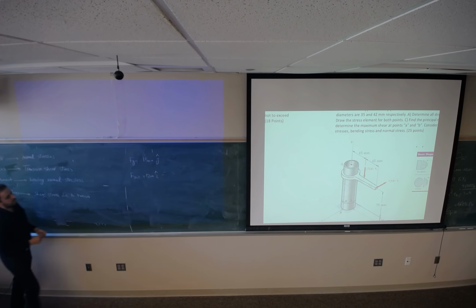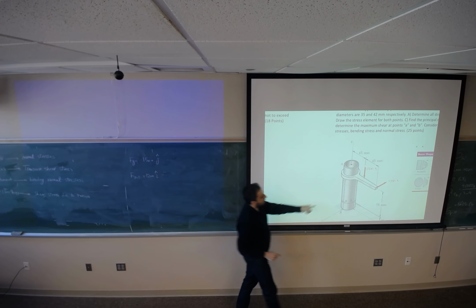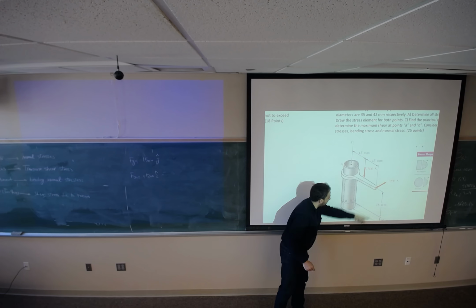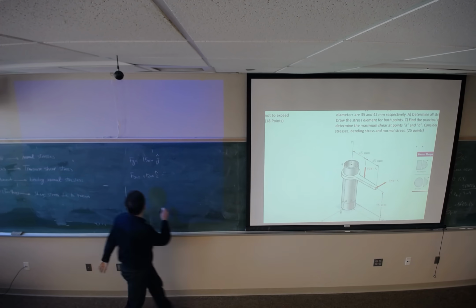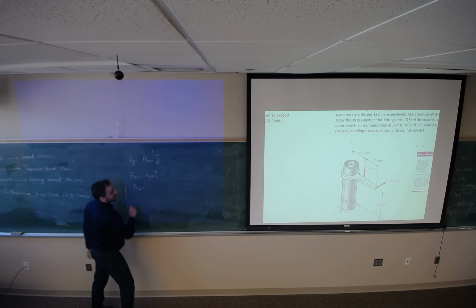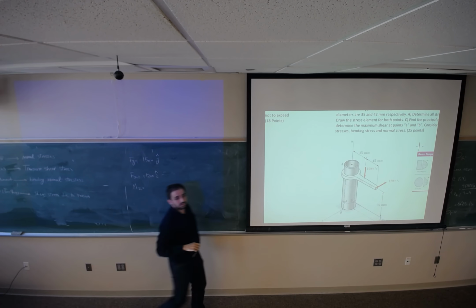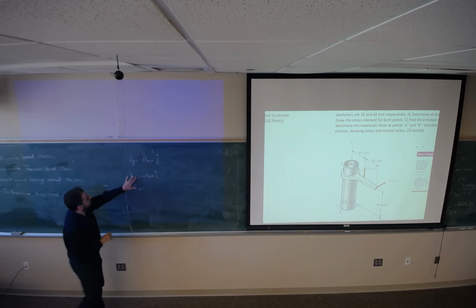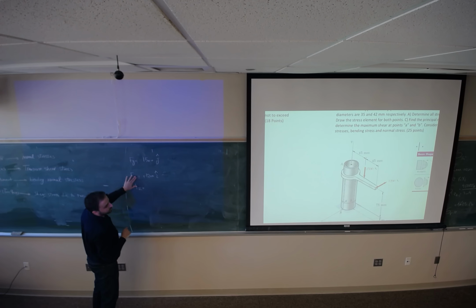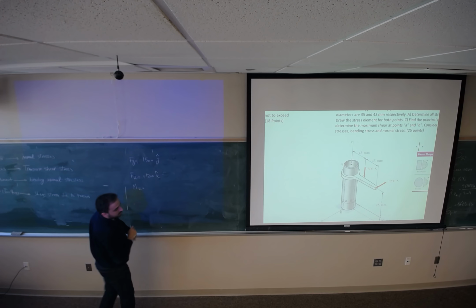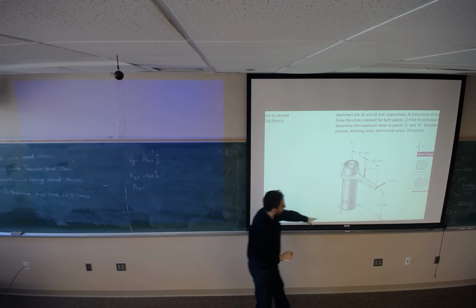Now bending moment. This force times this distance. Force in y direction, distance in x direction. So it's making a z direction moment, M_z. Shouldn't that be F_z, 12 times i? Thank you. F in z, in k. Thanks for checking.